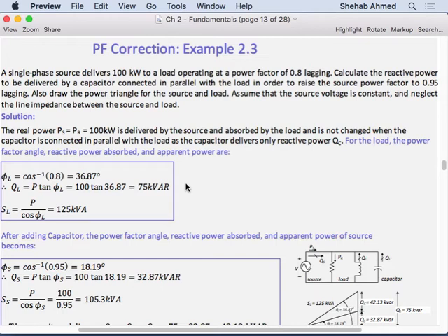So he will tell you, my transformer can process 100 volt amperes. Now you have the luxury. If your power factor is close to unity, then you're utilizing your transformer pretty well. If you have a very poor power factor, then you're not going to be able to deliver much real power through this transformer because all of it is reactive power, for example, right?